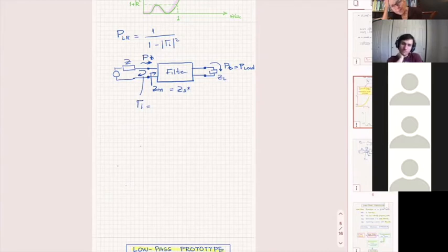The transmitted power is entirely real because the imaginary parts of the impedance cancel out. And not only that, but it is the maximum in that particular case you can get from the source. So even for conjugate matching, where your gamma in is not 0, you get the maximum possible amount of real power that goes inside your filter.